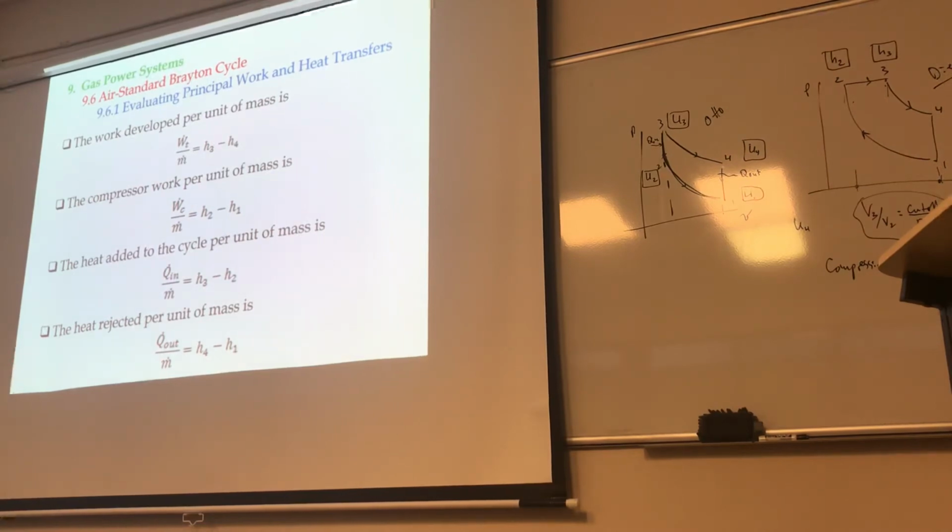So for you to analyze a Brayton cycle really ends up like finding 4 H values for those 4 states. Once you find those 4, done. Just like the vapor power cycle that you're going to be doing today. Once you find the correct 4 H's, then the rest is really just plug and chug, as they say.